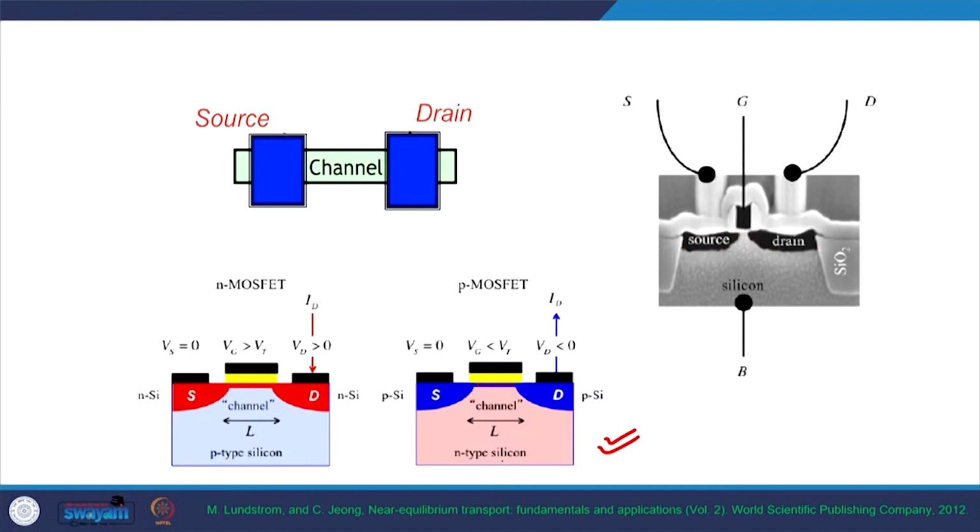So this is how it is drawn when we try to understand MOSFET, and there can be two types of MOSFETs. One is the NMOS and second is PMOS. In NMOS the channel is an N-type channel that is made out of electrons, and the substrate or the body is the P-type silicon, on which by applying a voltage on the gate terminal, or by applying an electric field on the gate terminal, we can make a channel, or we can make an inversion layer inside the material.